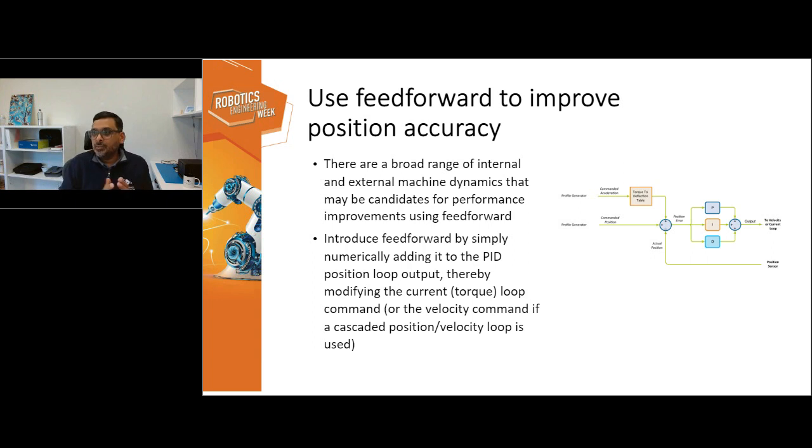We've also seen use cases where they're trying to design a micrometer or a nanometer precision machine, but they don't want to use an absolute encoder because those are expensive. So they tend to use cheaper encoders, but try to compensate for the inaccuracies of the encoder. If they can characterize it on the bench, they can put in a cheaper encoder, make the machine cost cheaper, and add these compensation tables to account for the differences to get to the precision that you need in the motion. So there are techniques you can do in the controller to offset and make the machine design cost cheaper.